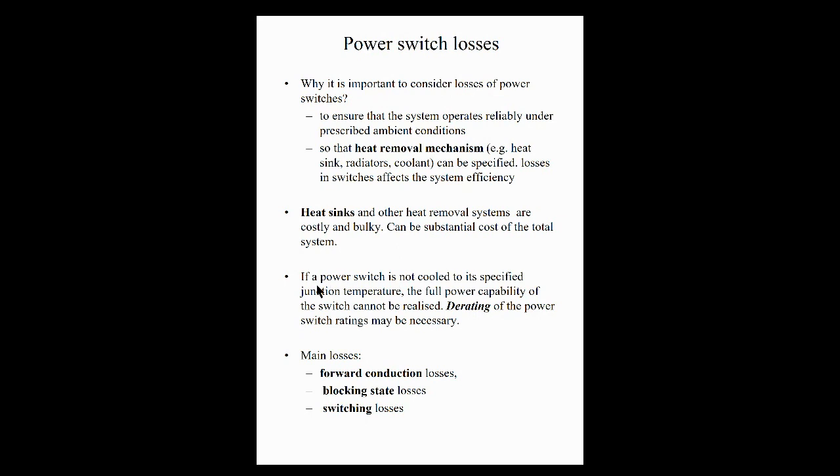You will also see later on how we're actually able to cool the device sufficiently so that they can operate at the specified junction temperature. Important to note that if this cannot be realized, then we'll have to do what we call a derating of these switches.